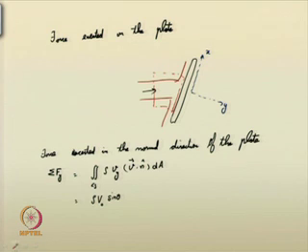Please note that this particular angle is theta, and this is V 0 coming here, A 0 here. So, rho V 0 sin theta in this particular direction, V 0 sin theta into minus V 0 A 0. This is the only quantity that is having a component in the normal direction of the plate.